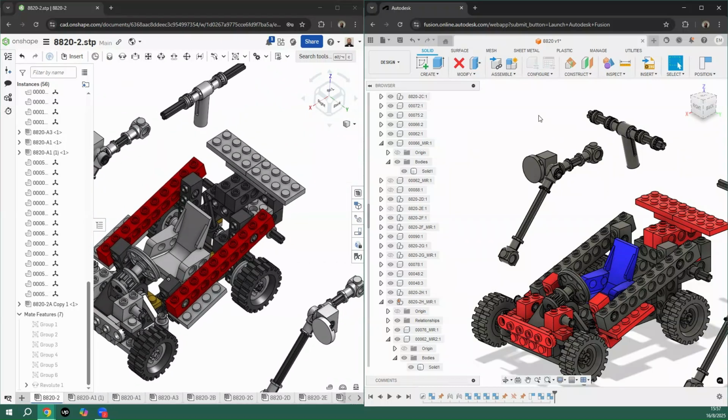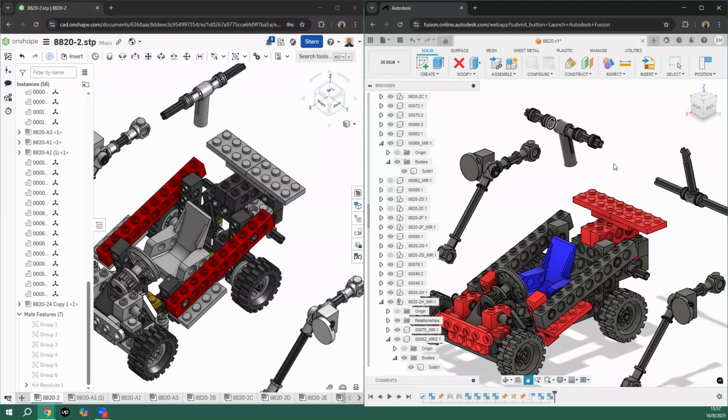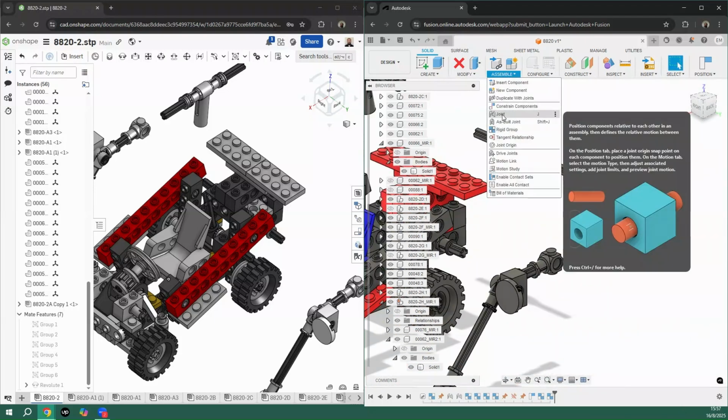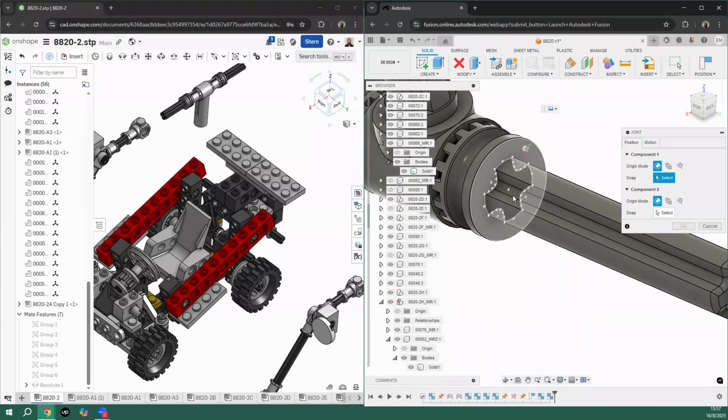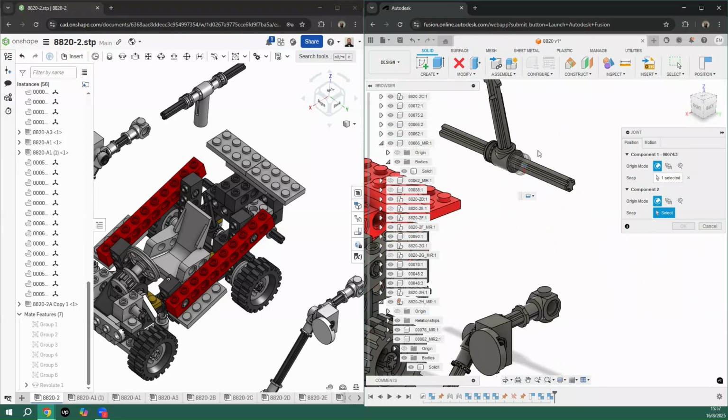Let's go inside Fusion 360. Okay, so we're going to use as well the joint command because we are comparing one to one. A difference that I find right now is that on Fusion you can put your cursor over a face, and when you hold the Control key on your keyboard, you can move along the different points for connecting the joint without them changing because of other faces that are in the way. So I will pick this one in here.